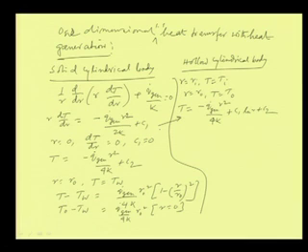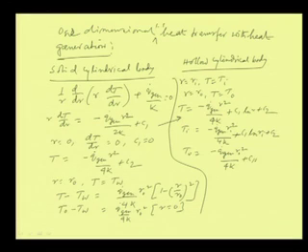And then finally, by putting the boundary conditions, we can write that T I is equal to minus q dot gen r I square by 4 k plus C 1 ln r I plus C 2, and T O is equal to minus q dot gen r O square by 4 k plus C 1 ln r O plus C 2.